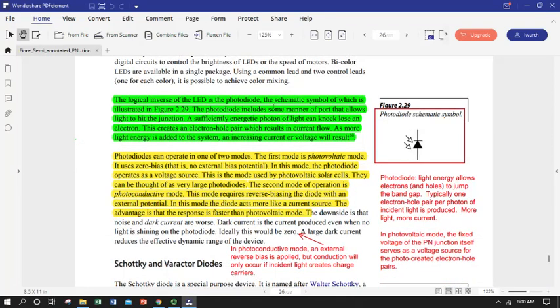Photodiodes. Okay, this is kind of the reverse of an LED, and this is very, very important for people who are looking at use of semiconducting materials for solar cells for power production. So the way a photodiode works is, if you think back about the nature of your depletion zone at a PN junction having a fixed voltage. We got that charge separation that came from our holes and electrons in our doped materials annihilating one another and creating that effective depletion zone that had a net positive charge on the N side and a net negative on the P side.